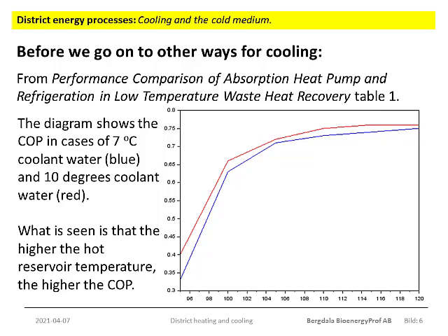Now, I cannot know how familiar you are with the thermodynamics of steam turbines. We will touch upon that briefly in the next module. But for the moment, I'd like you just to accept that the higher the hot source temperature for the heat pump, the less electricity can be produced. And that is because the hot source temperature is basically the exit temperature from the steam turbine.